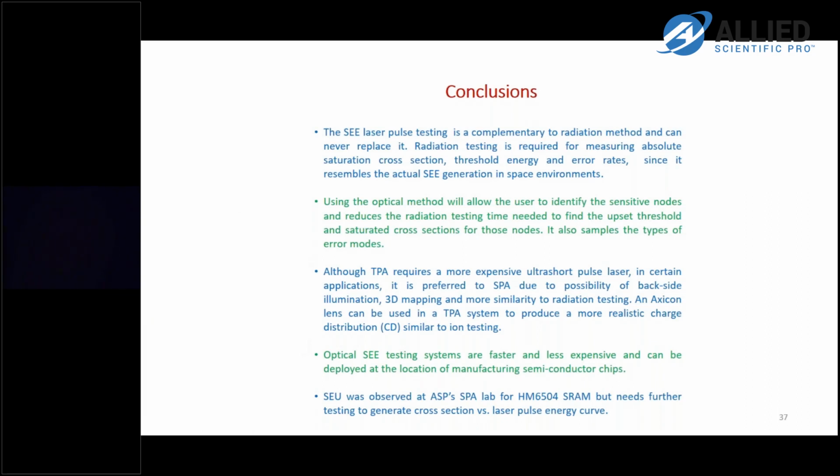So what did we learn from this talk? First of all, that the laser pulse testing of SEE is just a complementary method. It's not to be replacing the particle method because it cannot get the absolute value. So you need to do one radiation testing for calibration.